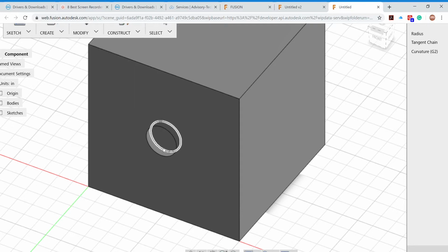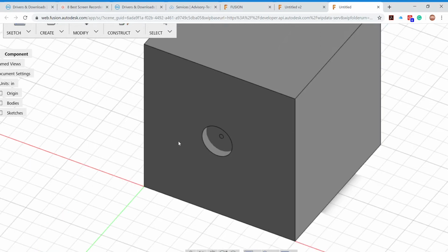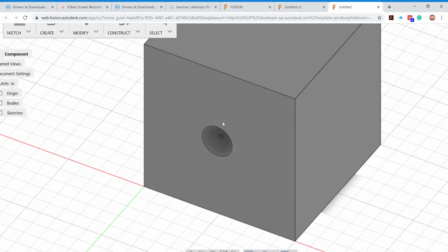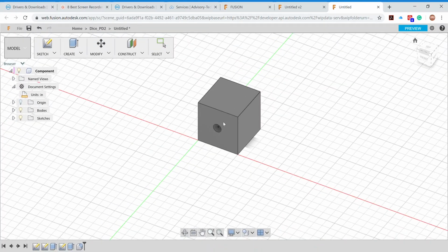One thing I noticed with students is if your extrusion wasn't deep enough, if it wasn't at that 0.05, a 0.1 fillet will not work. So again, we'll choose the inside, and the fillet needs to be half of the diameter, or the radius, of your circle. So if it's 0.2, half of that would be 0.1, and we'll type that in, hit enter. There's our fillet.